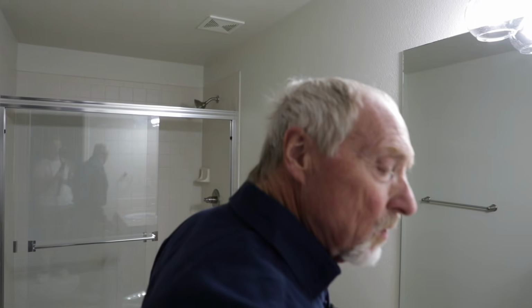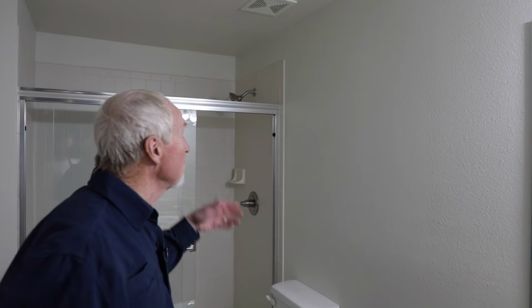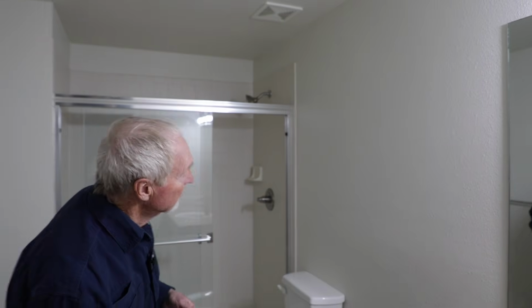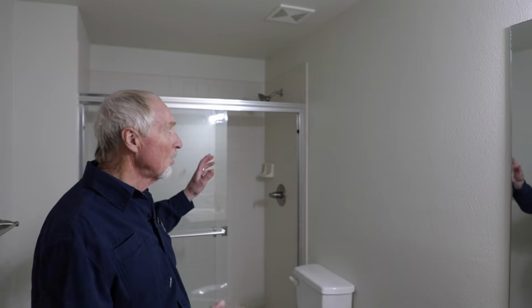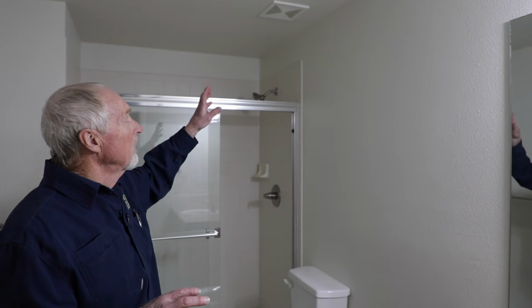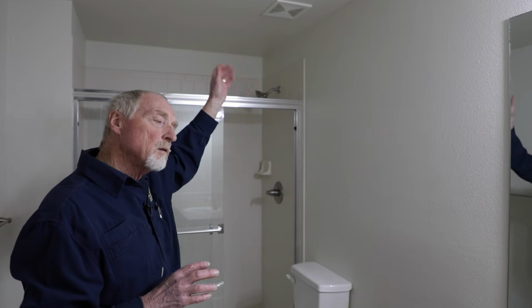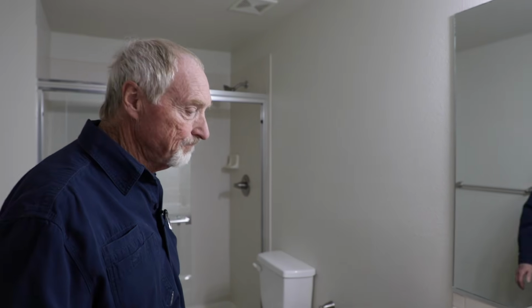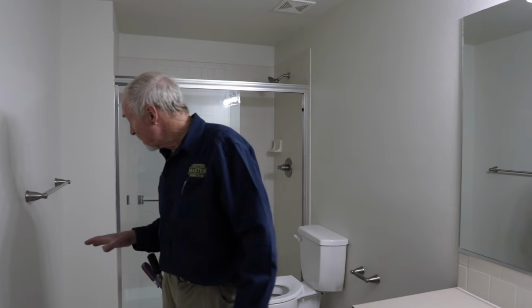Not required to determine if it's correctly terminated outside, but I'll usually look for that when I'm on the outside of the house to see if I can confirm that, particularly on basement finishes, more than other places in a house, they may not have ducted the vent fan to the exterior of the house like it is required to be. But right now, that looks good. So that concludes this bathroom, and we have some more bathrooms to check also.